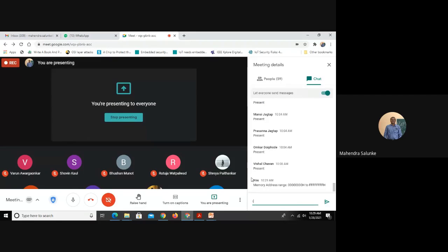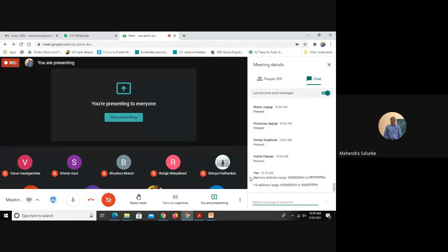And what I told you about the IO address range: your processor generates up to a maximum of the lower 16 bits in that case. So the IO addresses generated will start from 00000000H to 0000FFFFH. Now this is the IO address range. Based on this, you can see the same address range is there, so on the address lines it will have the same values.